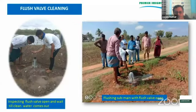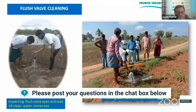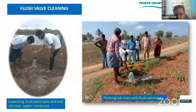And then of course, every drip system also has a pipe at the end which has a flush valve. The flush valves are opened and all the unnecessary particles are cleaned out, and you can see the person and the farmer also removing all the muck, and this is to be done periodically. If this is done, what will happen? The system will remain well intact.